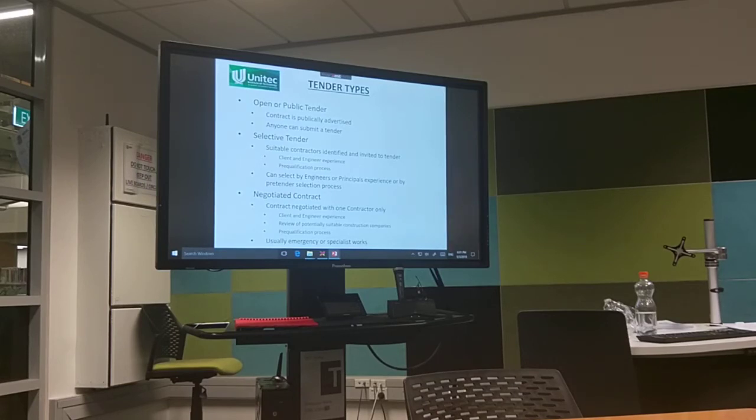So the next one is selective tender. What you do is you select contractors or construction companies. So it might be that the consultant or the client knows construction companies that are good value and asks them to bid. Or it might be that you go through a process. You say to everyone, look, we're not interested in prices, just tell us why we should invite you to tender for our job. So they'll put in their attributes. They'll say, we've got experience, we've got track record, we've got the resources, and then you look at them and say, well, they're pretty good, they're pretty good, they're pretty good. We will invite them to submit tenders. And so you keep it down to 3 or 4.